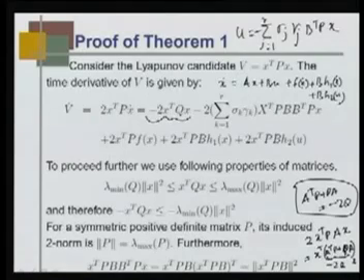Okay. So, from X dot I took care of A X. Now, let me take care of B U. So, B U is this quantity. How do I write it? B U, if I put it here, is 2 X transpose P B U, where U has B transpose P X, this one, and the other quantity is sigma j equal to 1 to R sigma j gamma j.